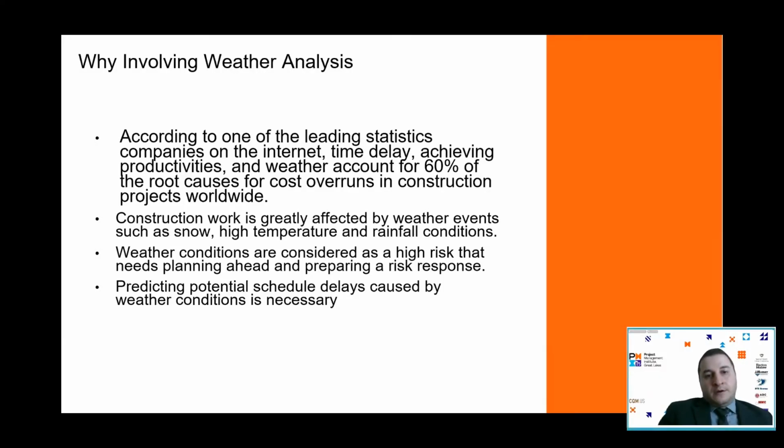Weather analysis is one of the most important aspects to be considered when creating a construction project schedule. Honestly, in my opinion, most contractors neglect that part, unfortunately, and that causes problems. When weather impacts the schedule, the major idea is that we do a change order, we get the extra days, the extra time, fix, that's it.